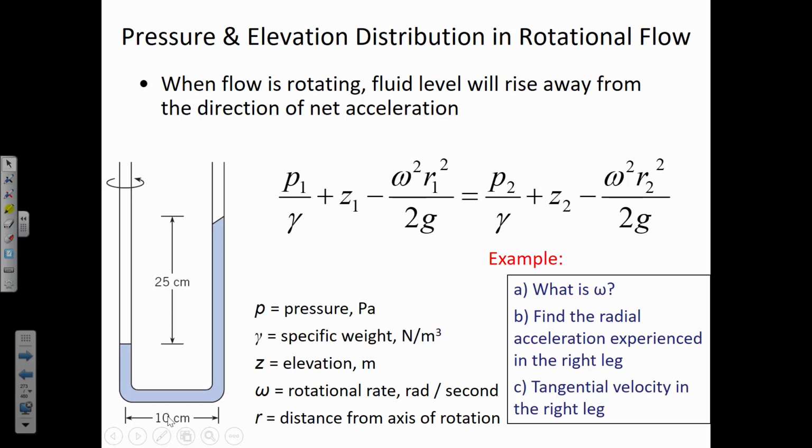Yeah, it's the same physical device, and it doesn't matter what location you're at, it's still rotating at the same number of revolutions per second. It may have a different tangential velocity, but since it's one physical piece, it's rotating around at the same rotational rate. So the omega is constant through the whole system.